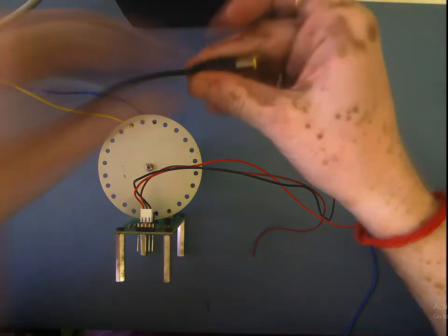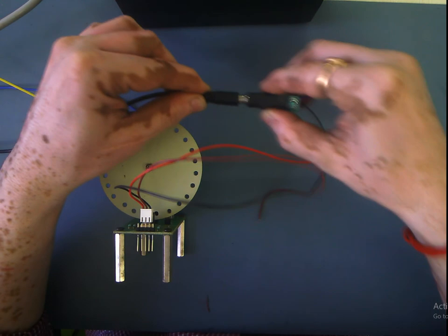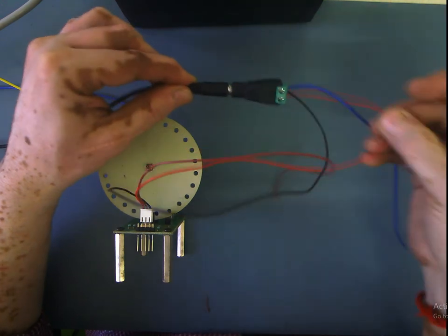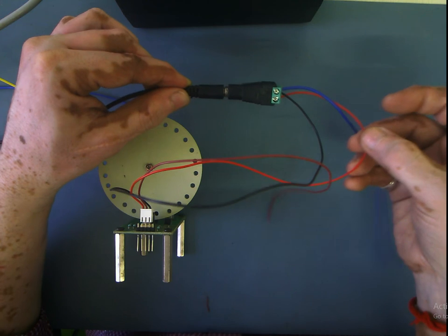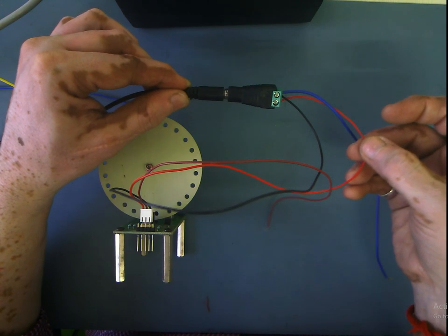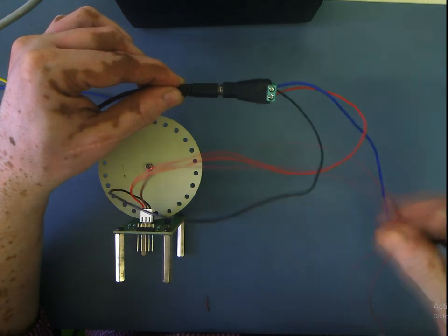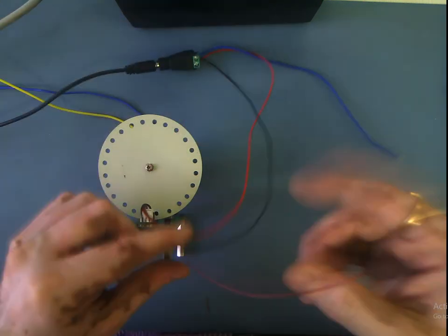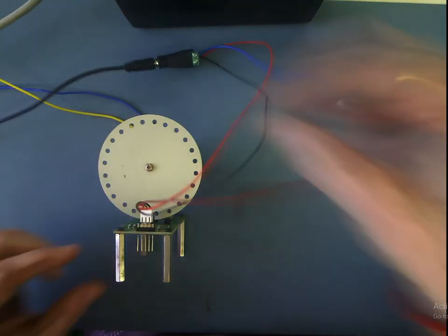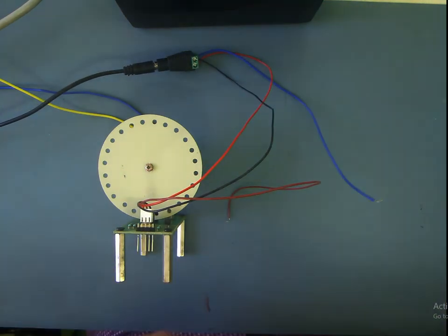So this is the adapter pin, and I'll be connecting it like this. This red wire will be supplying plus 12 volt. This black wire is connected to ground, and the brown wire is actually the output where we are expecting the pulse train, and this blue wire is nothing but ground, because we need a ground for our measurement.